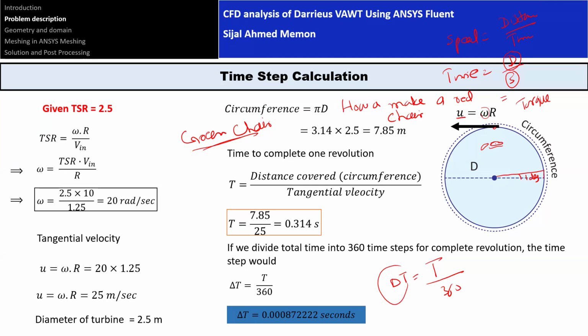Okay. And also keep in mind that CFD is not about the data matching with external data, but it's a process. So when you create three meshes, like one mesh, second mesh, third mesh, coarse, medium, fine, like that, actually we are comparing our own CFD with our own CFD. Okay. So why is this so? Because the scientists found that the meshing, boundary conditions, and your correct physics have a lot of effect on your CFD results. So you must first check these things. And once you are done with these things, then you can go for the other aspects of problem validation.